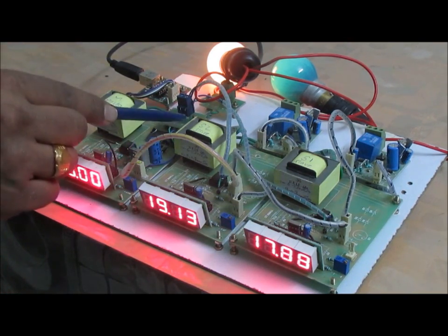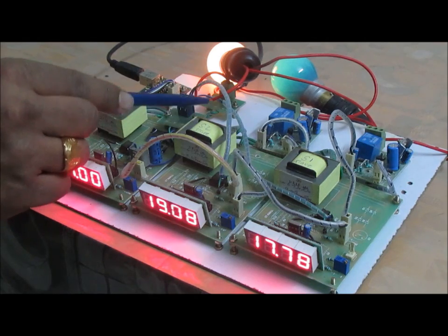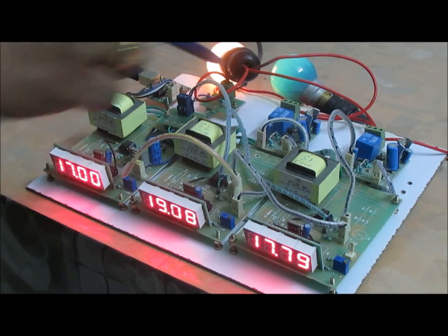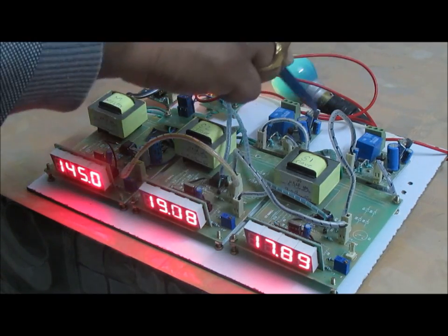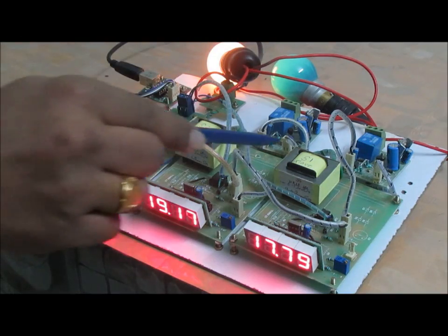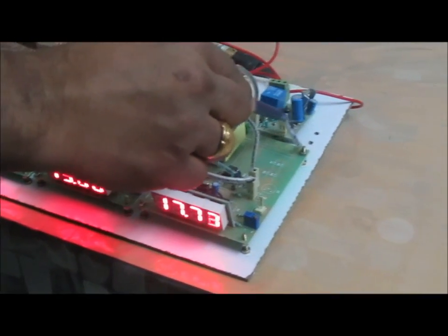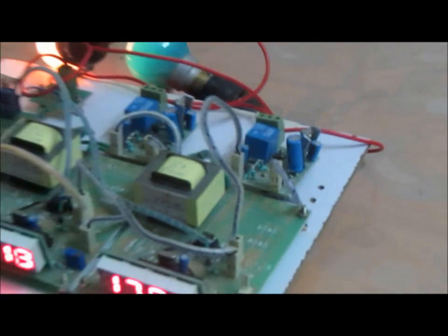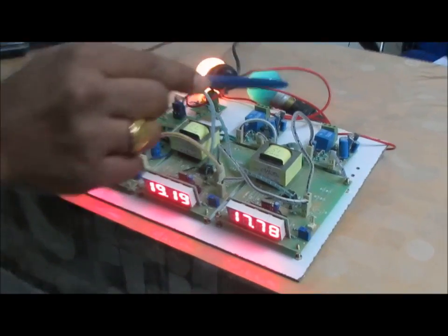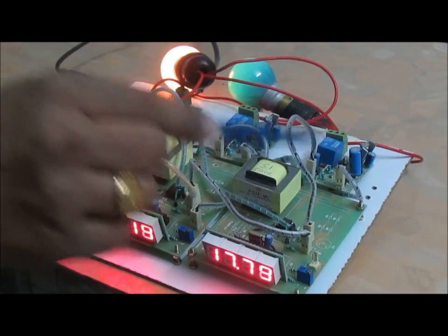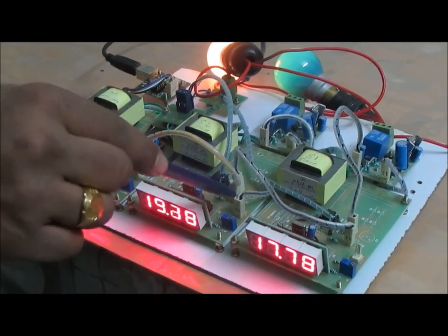And this transformer is also generating 0 to 5 volt DC via this 7805 circuit here, and this is being used for powering this relay. And similarly here, this transformer is generating 9 volt AC, then it is converted using this bridge rectifier circuit, then this regulated power supply, then this relay is getting power. And this relay is getting its control signal from slave 2 via this point, and this one is getting from this point here.